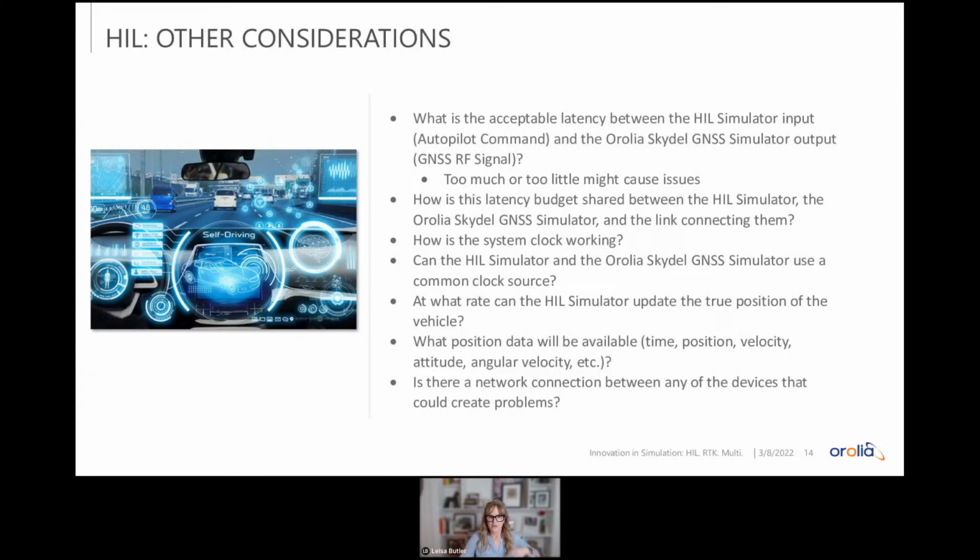So what else do you need to consider when you're looking at a HIL system? What is your use case? Based on that use case, what's the acceptable latency between the HIL simulator and the Orolia GNSS simulator? What's your budget? What's too little? What could cause issues?